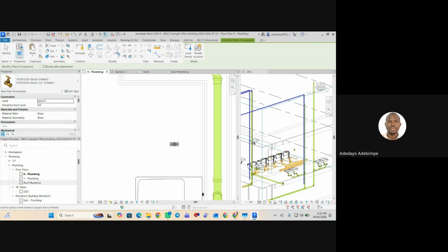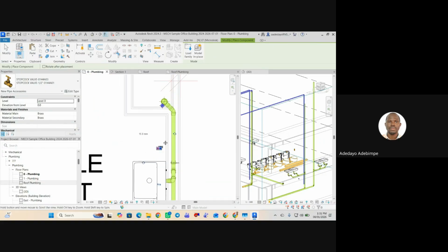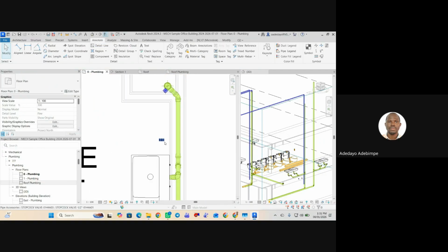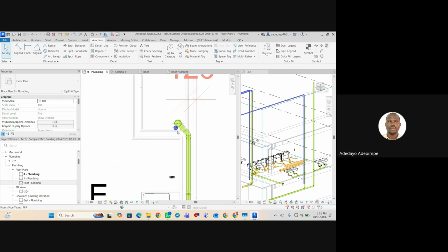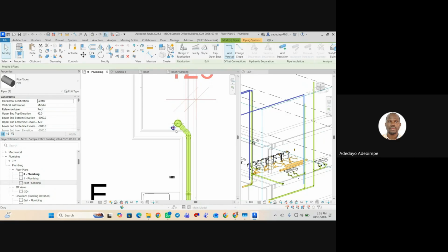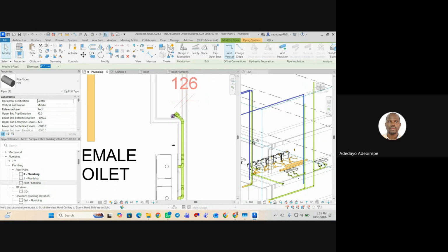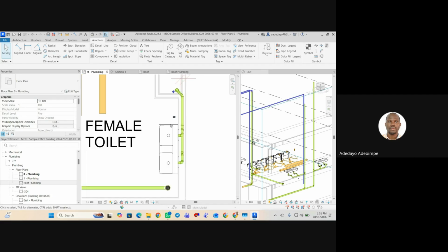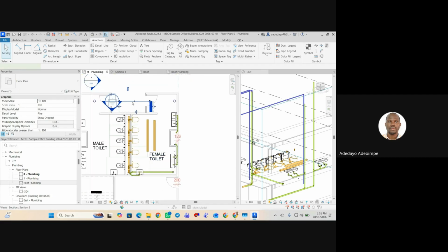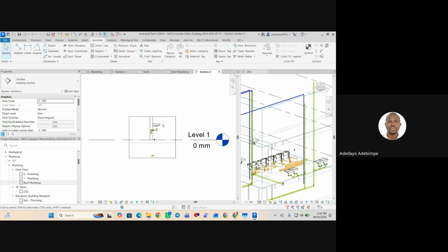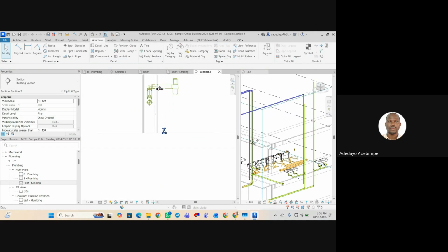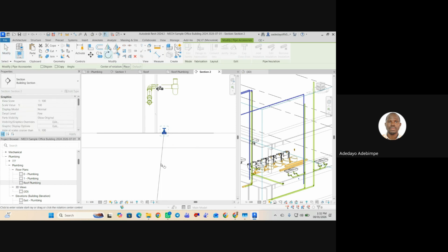Okay. So this is my stopcock. My pipe will come in at a. Permit me to shoot this guy so that I'm not having any clashes. Now, I need my small section to align this stopcock properly. I'll click on this, RO rotates, do 90.